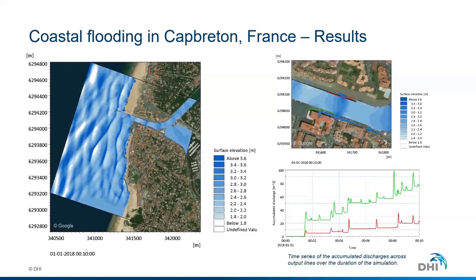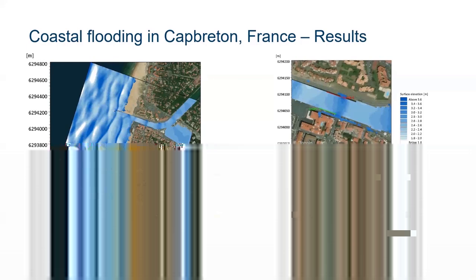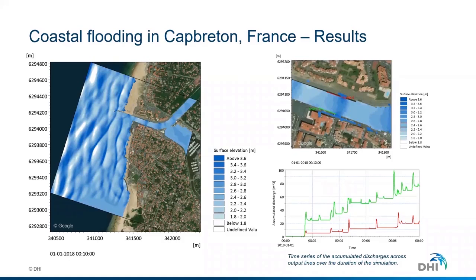So you are not trying to do any boundaries between the beach and the water domain. Here you can represent the landmass as bathymetric features and just let the model handle the overtopping and the rundown of the waves. So you don't have to draw these lines along the beaches and the channels. You can model those as bathymetric changes within the model.